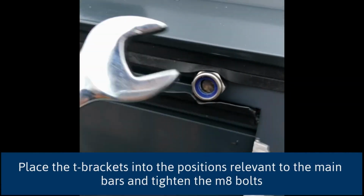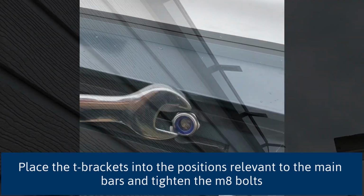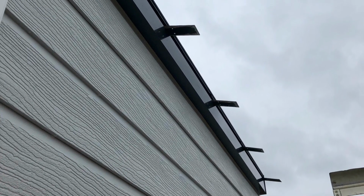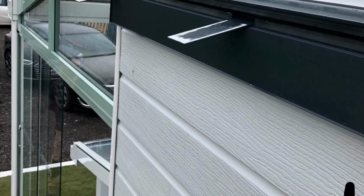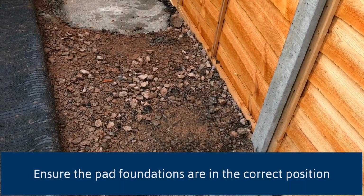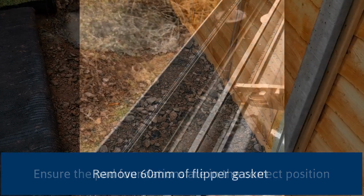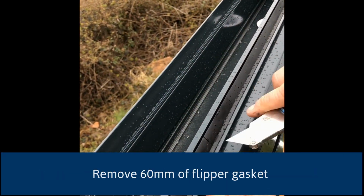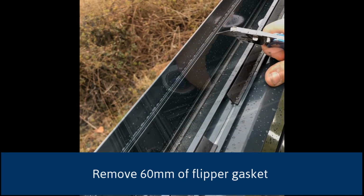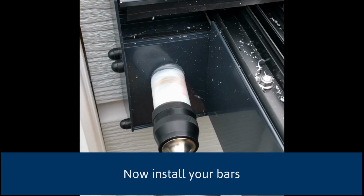Now place the T-brackets into the positions relevant to the main bars and tighten the M8 bolts as shown. Ensure pad foundations are in the correct position. Remove 60mm of flipper gasket as shown to ensure the plates sit flat with the T-brackets at the end of the bars. Now install your bars.